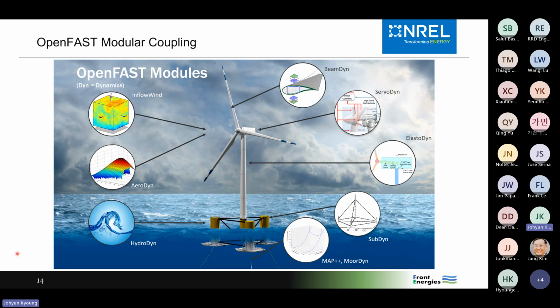And for the substructure, we have our SubDyn module. That's basically a linear beam frame finite element model. We have beams as the basis, but we also have various joints. You can have pin joints, ball joints, universal joints, also various kinds of cable elements like taut lines. Because it's meant for the substructure, this one's purely linear formulations. We have the rigid body rotation plus linear elasticity, but you can represent full flexibility of the support structure with SubDyn.